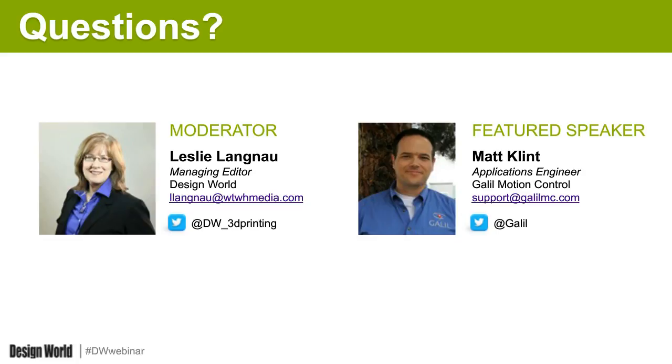Are there plans for 1 gigabit per second Ethernet or EtherCAT communication in the future? To my knowledge, no. However, I'm not involved in the development of the EtherCAT standard. At this point, the mitigating factor for EtherCAT communication is how fast the EtherCAT master can put information out. If the EtherCAT master doesn't need to put out gigabytes per second of data, then there was really no need to move to that yet.